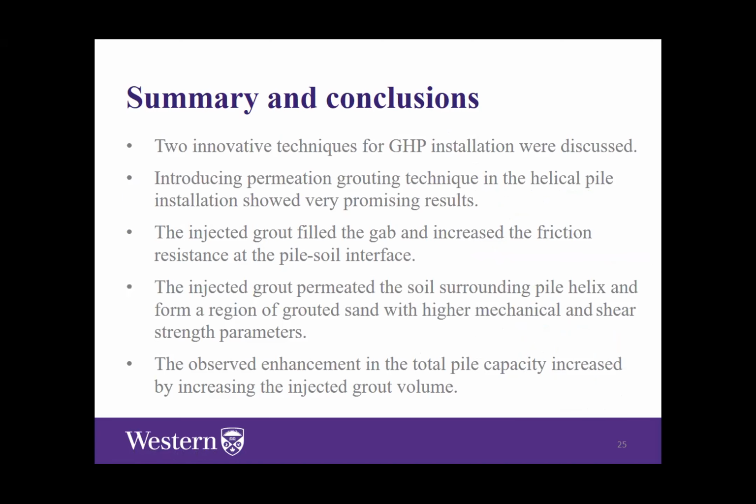So we will end up with the summary and conclusions here. We developed two innovative techniques for grouted helical pile installation. Introducing permeation grouting techniques in the helical pile installation shows very promising results. However, we still need more research, because we did this on a very limited number of piles. I believe it was 8 piles.